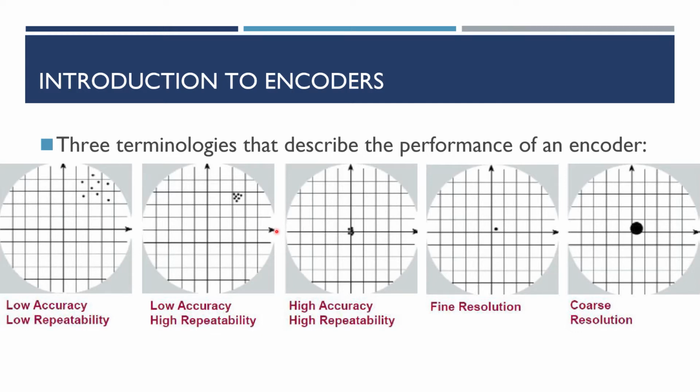Typically, repeatability is the most important factor we may be concerned with when we choose an encoder, because the accuracy can be compensated with a predefined compensation table, so that the object to be controlled is requested to move more or less than the displacement in ideal conditions at every position, to achieve higher accuracy. This compensation table relies on the repeatability of the system. It's because the displacement of the object to be controlled is subtracted by a certain value when commanding to a certain position with compensation. And if the repeatability is low, the position error may still exist.